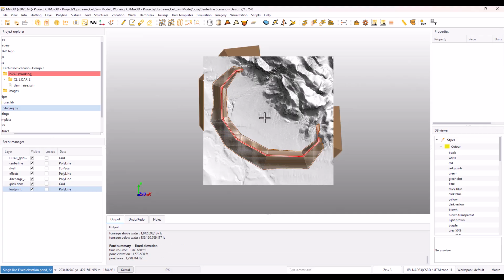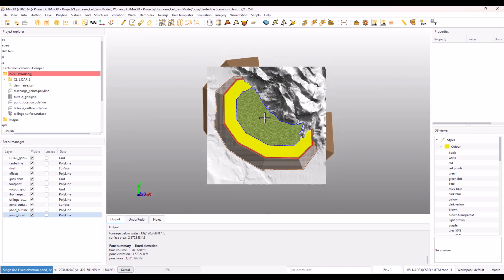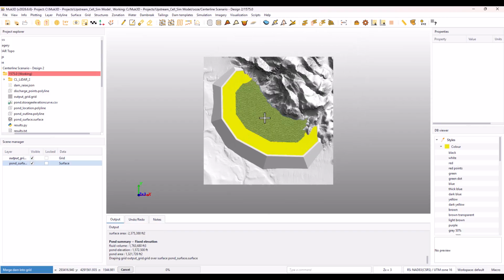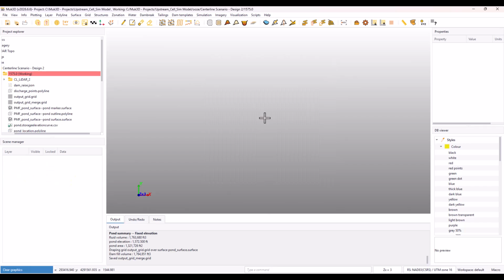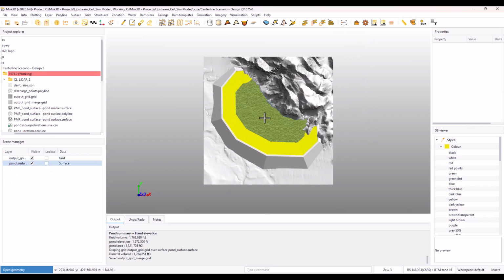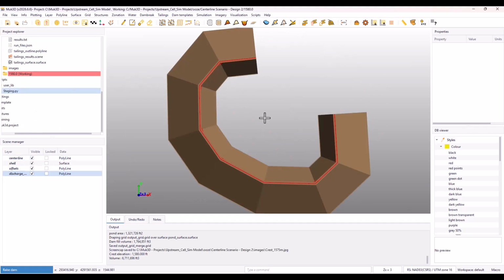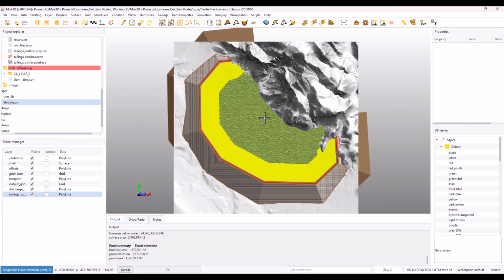sequence. Raise the dam, deposit tailings. You're maintaining your freeboards, you're measuring the placed tailings, the pond volume, the remaining storage capacity. You create an image of the TSF after each lift, and you place all the numerical outputs into a tabulated spreadsheet that gets stored in a centralized directory. 5 raises, 10 raises, 15 raises, it doesn't matter. You fill in the specifics in the user interface and it produces a folder full of results.